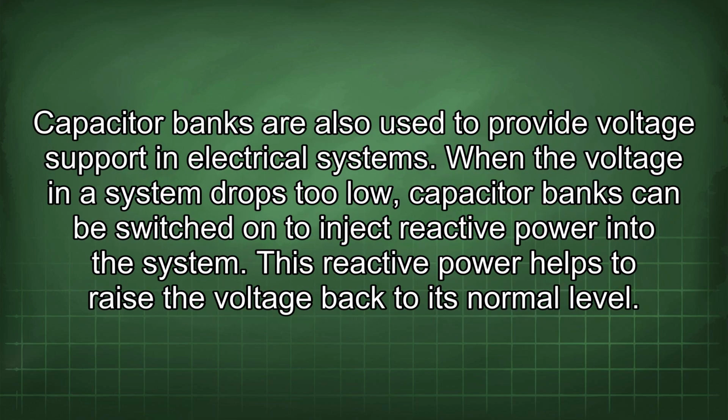Capacitor banks are also used to provide voltage support in electrical systems. When the voltage in a system drops too low, capacitor banks can be switched on to inject reactive power into the system. This reactive power helps to raise the voltage back to its normal level.